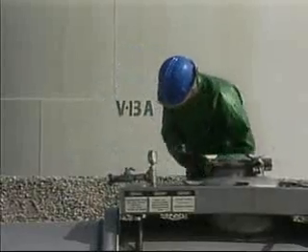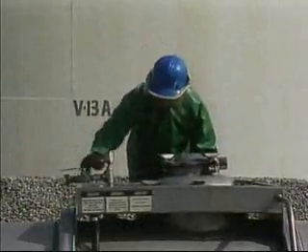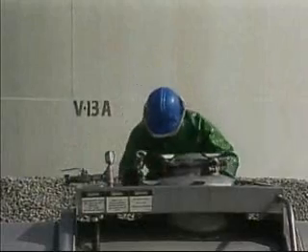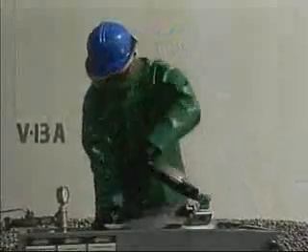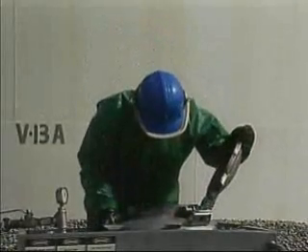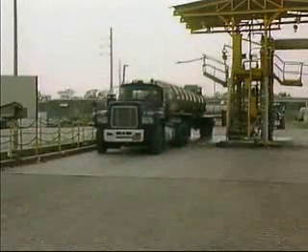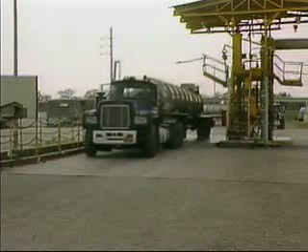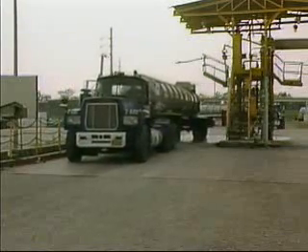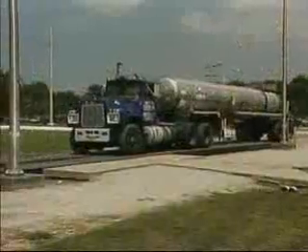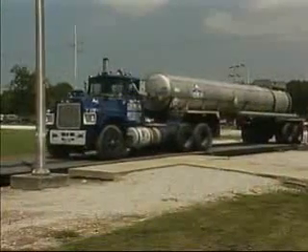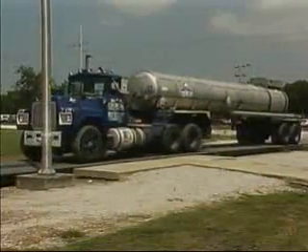To bleed excess pressure off the tank, the operator temporarily reopens the air valve. He also opens the manway and makes sure there isn't a significant amount of liquid left in the tank. The operator then continues to follow standard procedures for safely and properly disconnecting and releasing the truck. Finally, the empty tank truck is weighed before it leaves the facility to determine the amount of product unloaded. That's one procedure for unloading a tank truck.